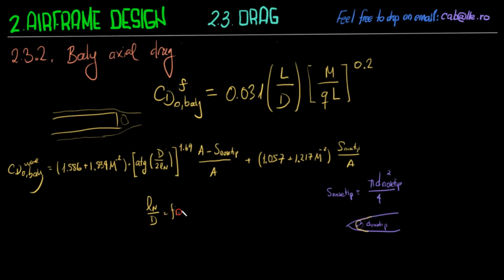So, typical ratios for fineness ratio. This is the main parameter here. As you can see, this parameter here is really low because the curvature you're going to give it is pretty low. So this is a big term related to the wave drag, and inside here this is basically close to 1. This is just Mach terms. Can't do much about it. Well, we can, but the geometry terms are here, and the geometry only depends on the fineness ratio.